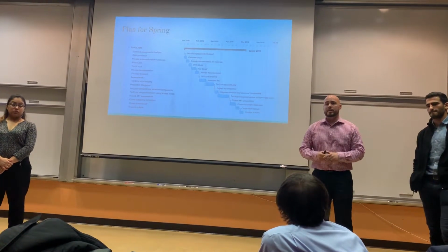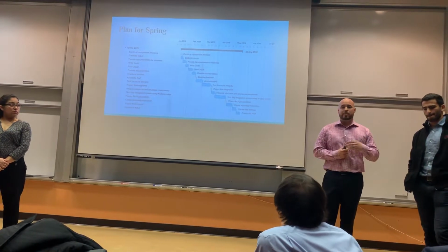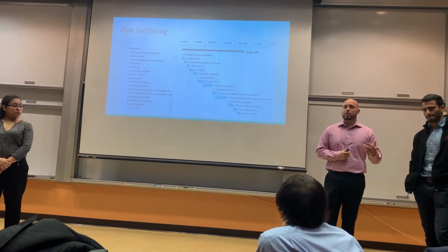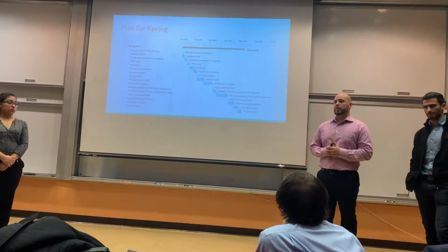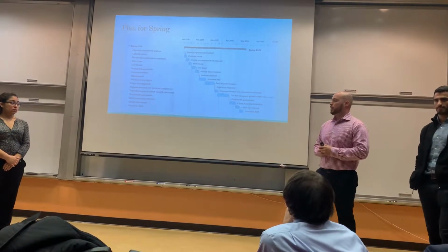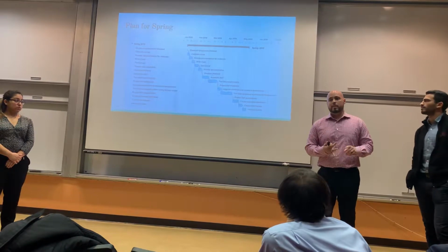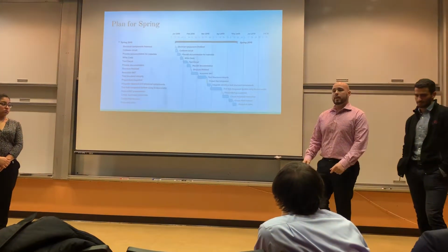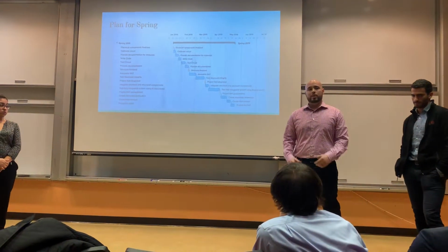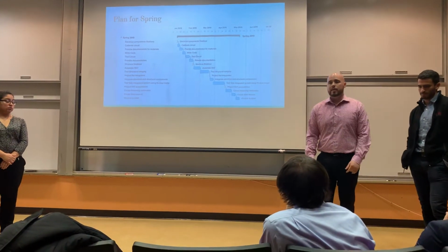And then we will actually be conducting our final testing after the C-class motors on the N-class motor to make sure that it's properly obtaining all the critical design criteria, such as the force versus time curve, temperature at the nozzle, and the maximum thrust. After successful completion of the testing of the N-class motor, we will then present the final product to the AIAA team.